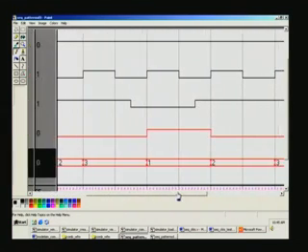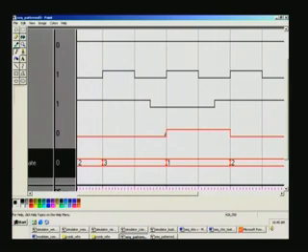So, you can see now we are in state 3. So, you can see once again that all outputs take place only at the following clock edge, right, being a synchronous machine. If it were a Boolean expression, then it would have taken immediate effect, right. So, being a sequential circuit, it will always take place only at the positive edge of the clock.